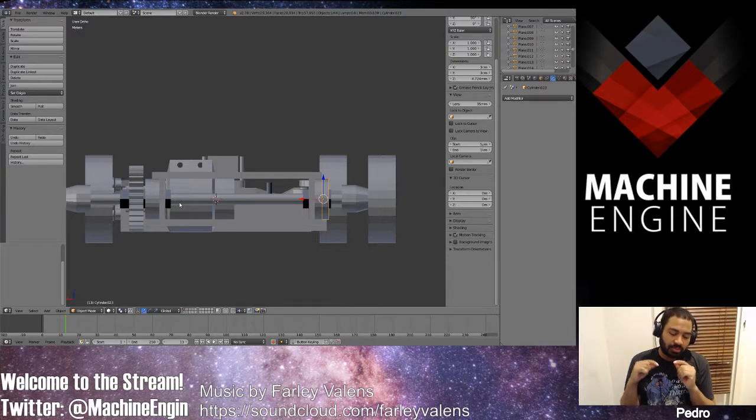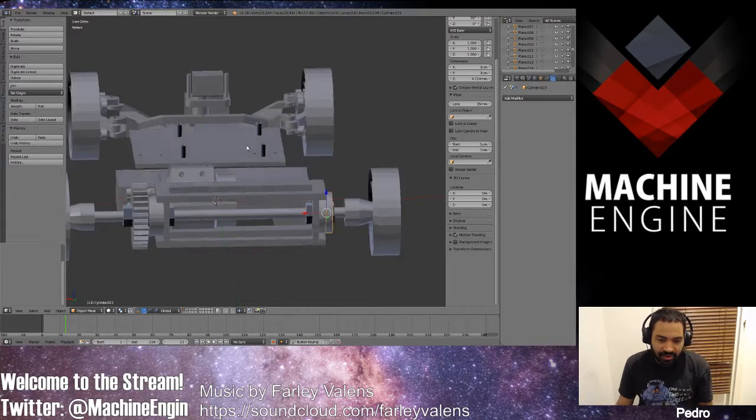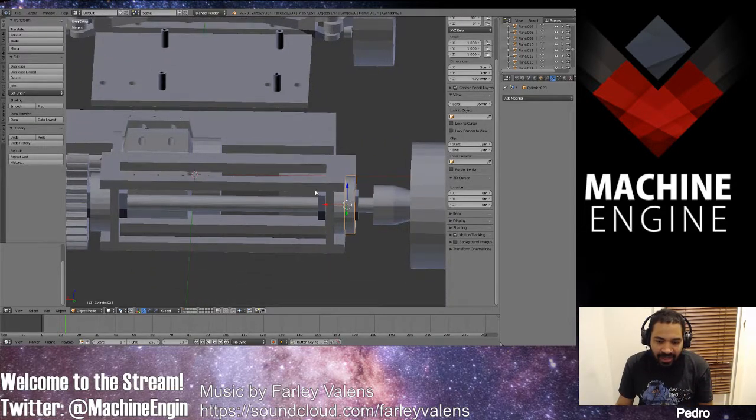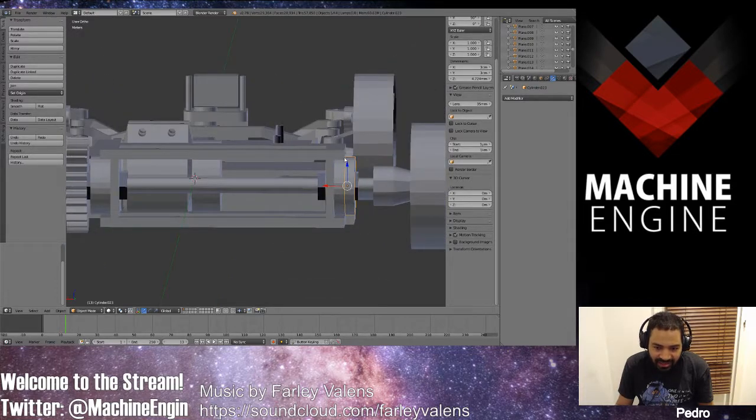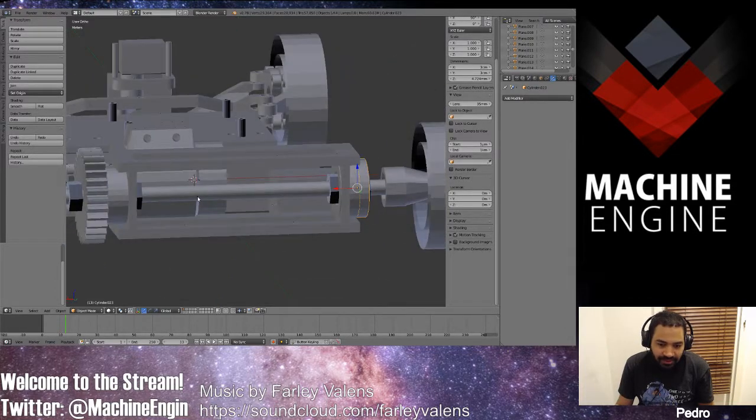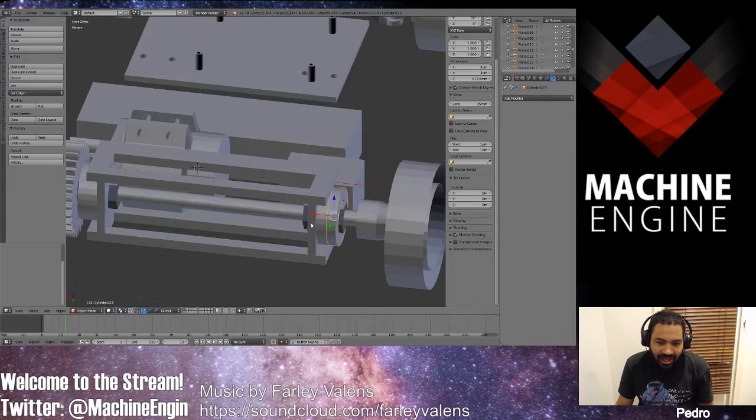That's why I always print any parts that have circles in them that need to be perfect, because ball bearings are going in there, face down, so the printer paints the circle like that and gravity doesn't affect the shape of the circle. That's what I do. So you have to keep that in mind when designing this. And I did that here because these circles, like here, are flush against it, so it's not going to affect it in any way.